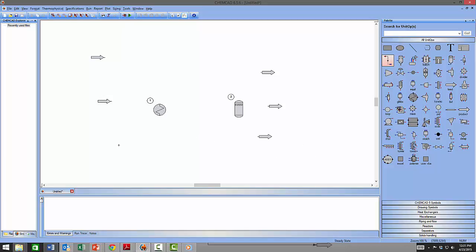If you move the cursor over the unit op or the equipment, the inlet and outlet connections become activated as blue and red dots come to life. If you hover over the heat exchanger, you can see all inlet and outlet stream connectors. Here the inlet, here the inlet, here the outlet, here the outlet. And also if you move your cursor over the flash drum, the feed only has an outlet, and then the product only has an inlet.